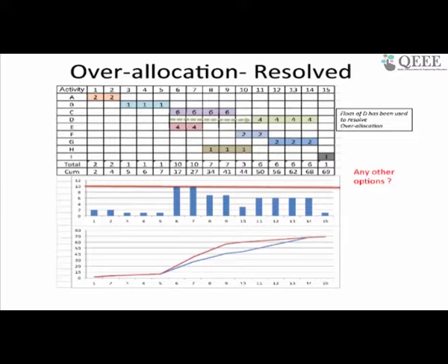If I were to actually do a resource leveling, I would say, no, here I have lots of peaks and dips coming. My resource leveling would be to try to keep a uniform resource over the whole period. Ideally, I don't want to have peaks and dips. Either I want a flat resource level, or I want resources gradually increasing, a kind of parabolic shape. That can also be thought of, but you will find that the algorithms required for that are fairly more sophisticated. We will touch upon that. We will not go into detail.